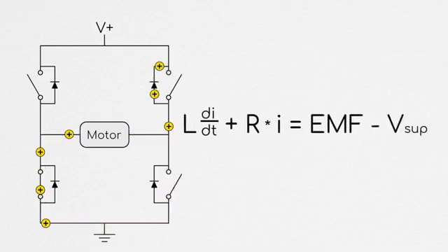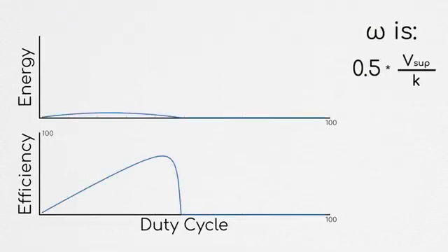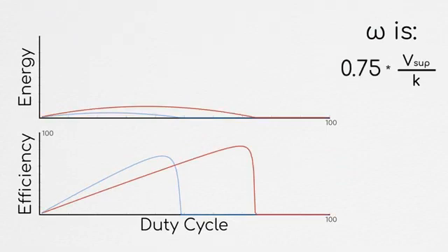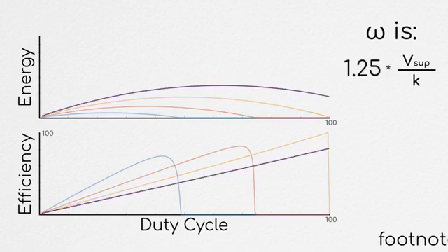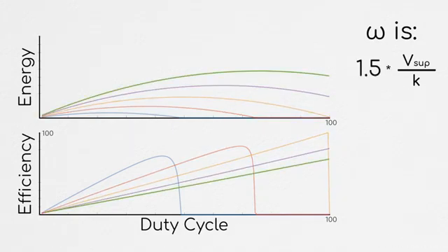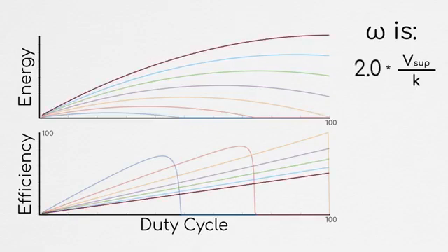Then we will switch our FETs such that this current, which must decay smoothly, has to run back into our supply. It's worth noting here that the way you configure this second part of the period will vary depending on what your switching scheme is and potentially with how fast your motor is turning. It's also worth noting that depending on circumstances, it's sometimes possible to regenerate more power using this method than could be achieved with the non-PWM method described earlier, even if your motor is rotating quickly enough to allow for either. This may seem confusing, but it is possible as, while the PWM method will have lower efficiency, it's able to operate with higher currents and thus can take more total power out of the mechanical system.